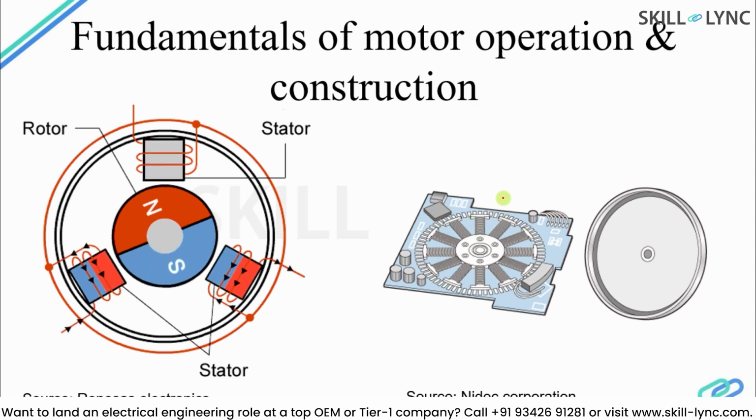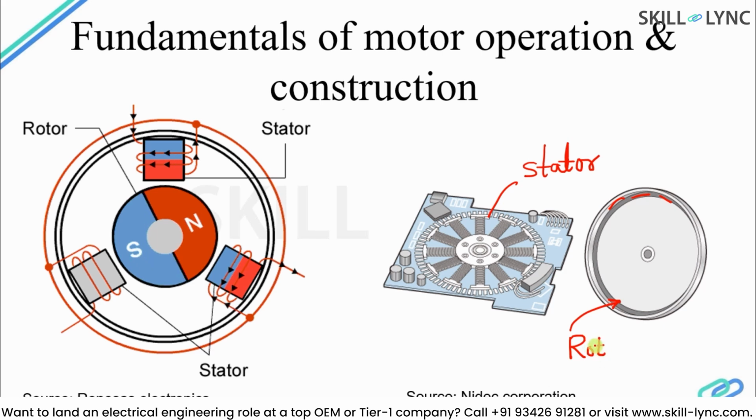What you are able to see are the stator part and the stator coil, which remain fixed, and the rotor is this disc, and there will be a permanent magnet mounted over here. So this is a permanent magnet rotor, and the difference between this concept and this product is that here you have the rotor inside the stator and here you have the rotor outside the stator. Many applications consider the rotor outside, and this is just a simple application of a hard drive.